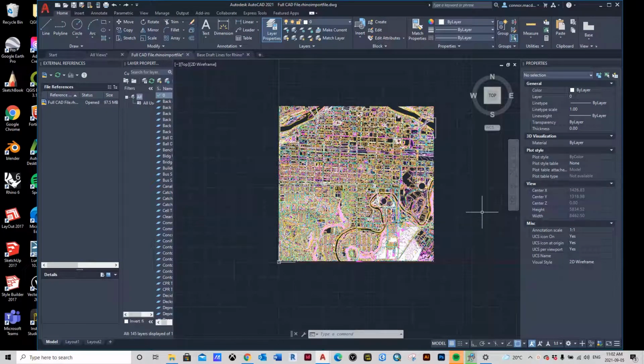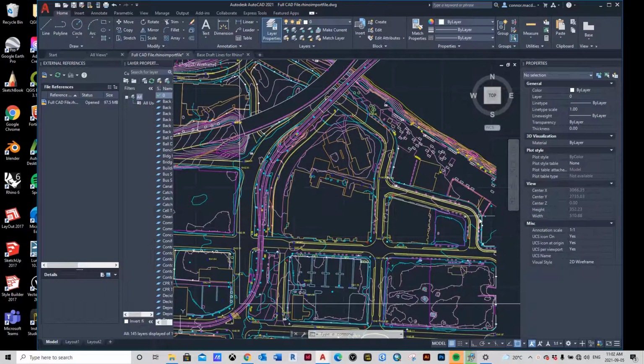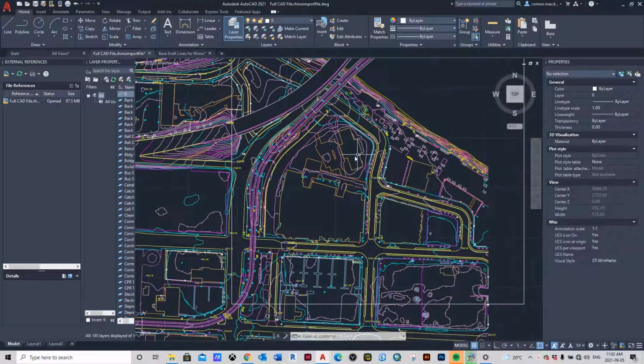So when we begin this whole process of taking CAD files and making them viable to import into Rhino, the first thing you're going to notice is, I would assume all of you probably have this base file, which is pretty much the nuts and bolts of the entire area in Calgary. The big thing here is we want to start by paring all of this down, because this is way too much information, and the project scope for this is really just this little space in here, if you can all see that, hopefully with my cursor.